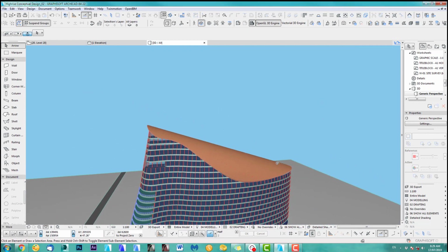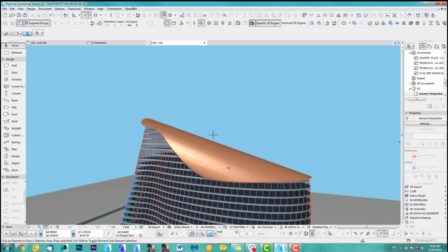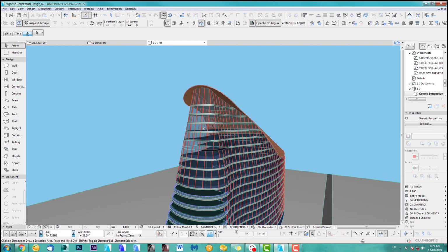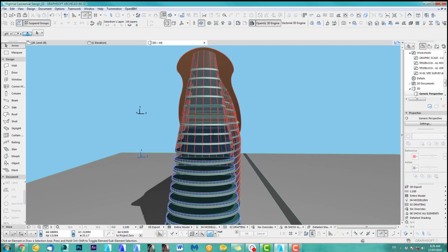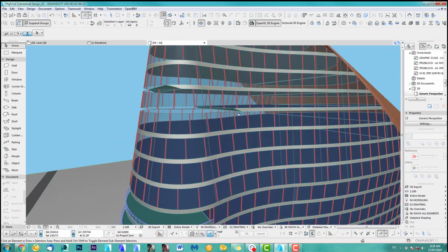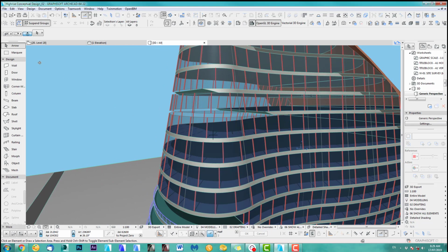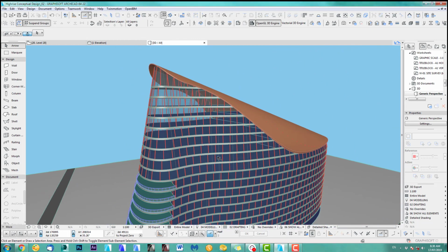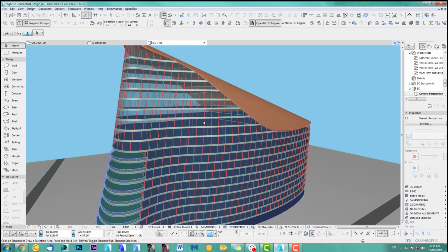But the next bit is now, let's put in some windows. That'll be exciting because you want to look out that side too. How do we do this? Again, the shape, I took the shape from here, so it's overlapping here. Again, it's all done. Oh, now I just saw that we cut 2 of those off. Can you see here? That's very annoying. How do you fix that? You click on this one, you go in there and you don't trim it. And you do this one, go there, and you don't trim it. Alright, cool. Beautiful.